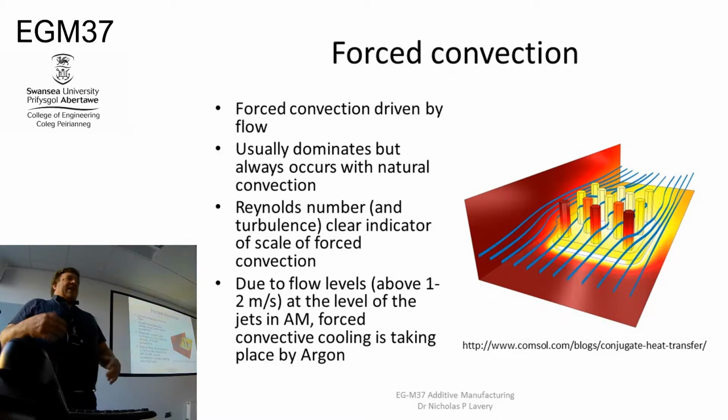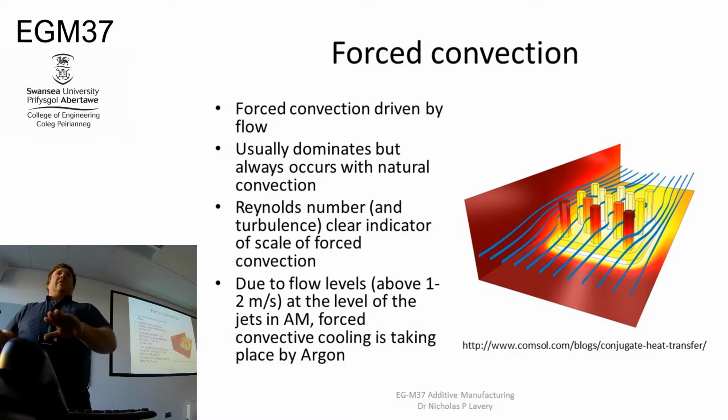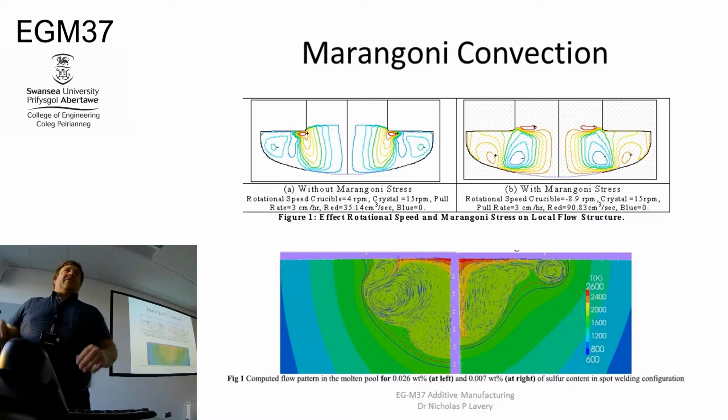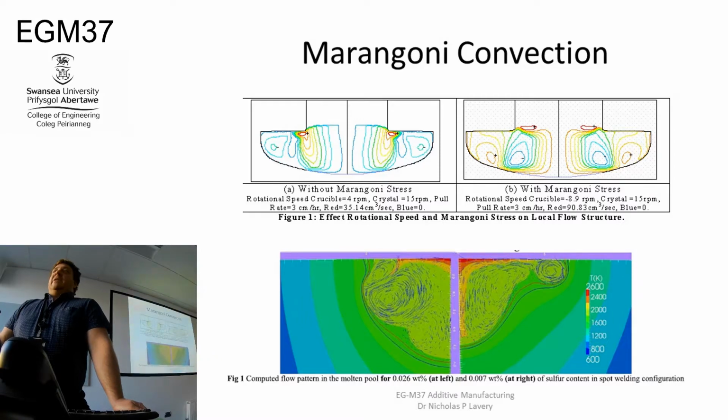Okay. Forced convection is definitely something which we find. So we've got cold gas coming in at ambient and going over relatively hot plates at 170 degrees, or localized hot spots which are right up to 2,000 degrees. So you're going to get a forced convection between that area and the gas. Both of those are important from the perspective of being able to design a cooling rate, a transport rate for the gases, and making sure that you're not forcing any powder out of the way.